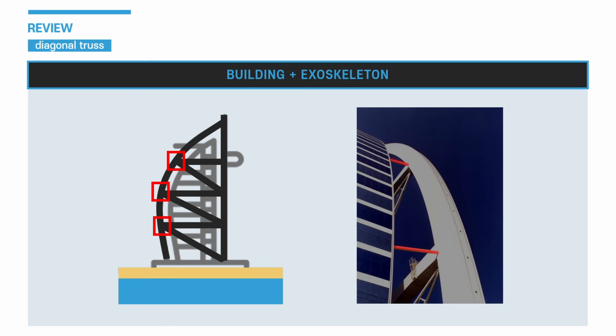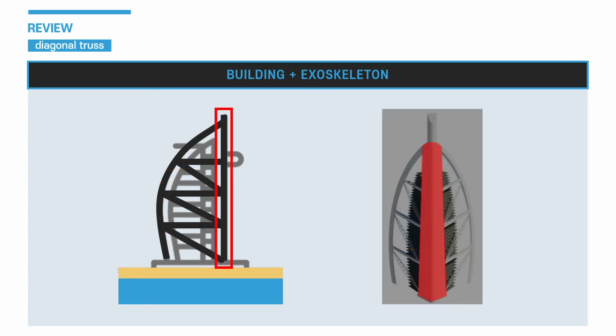For the first connecting part, rear bracing and exoskeleton, the exoskeleton was connected in a straight line with 3 girders of rear bracing frame to deliver the lateral load on the building to the exoskeleton. Second, for core and exoskeleton connections, the exoskeleton was completely connected to the core from the start of construction.